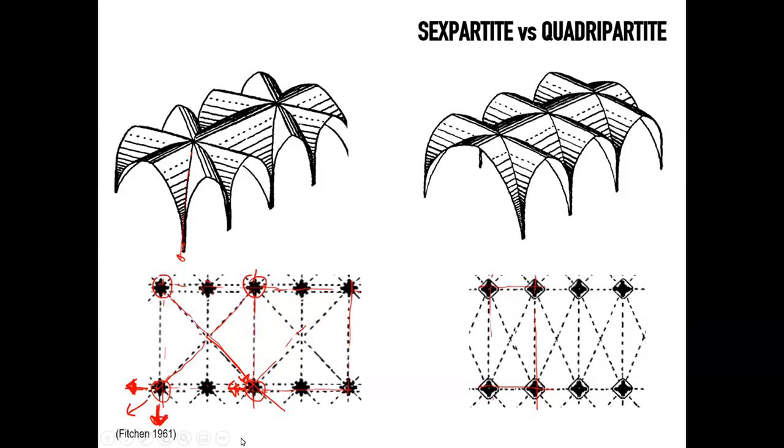There was this temporary need to prop the structure. Whereas sideways, perhaps the problem could have been resolved by building the buttresses first and preventing the lateral load. So, normally you think that the cathedrals have to discharge horizontally, which is why they have all those flying buttresses. But when they are built, they also need to be restrained in this direction, because once it's all built, each bay is counterbalancing the next bay. But before those bays are built, what's happening?